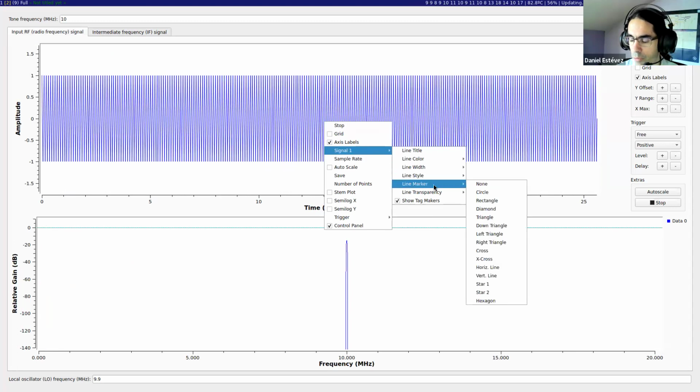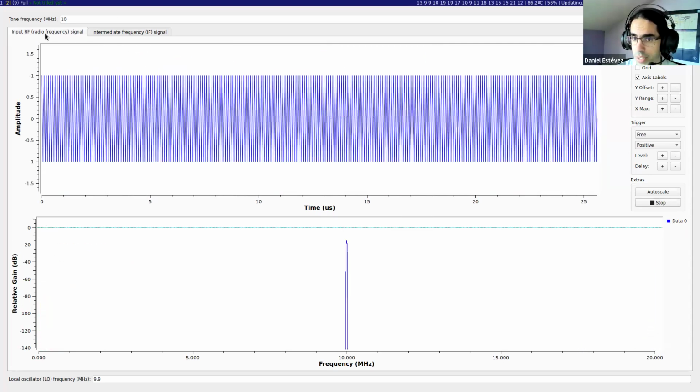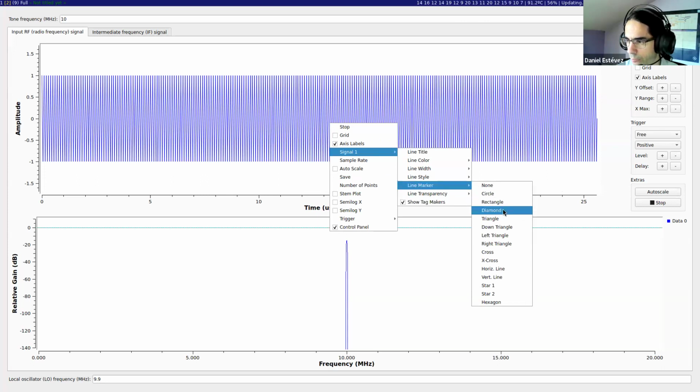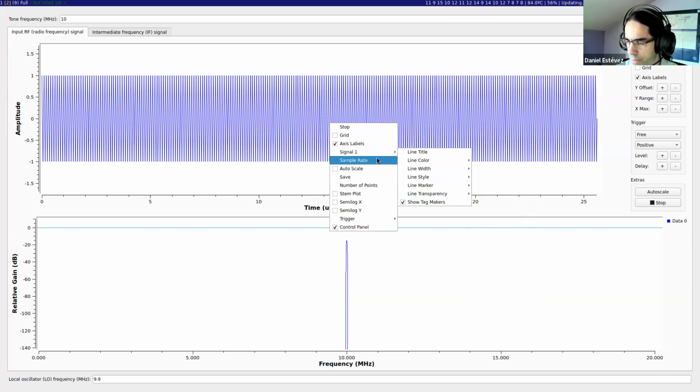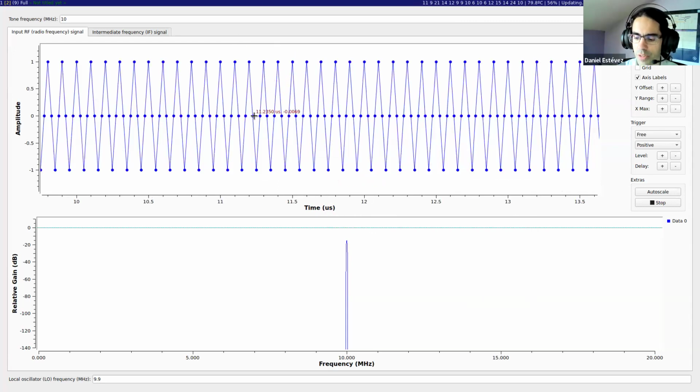The voltage of this red signal, which is an electrical signal, comes into some piece of electronics to the ADC, and the ADC is taking measurements of that voltage very fast, maybe 1 million times per second, maybe 3.2 million times per second, if we use the maximum sample rate.